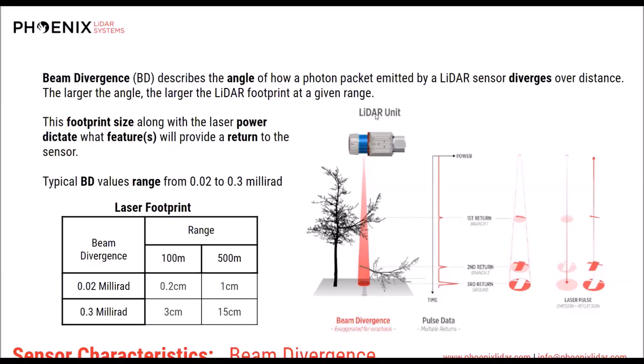But in terms of that absolute number, that's a pretty tough one, especially given the specific project areas, because you want to target clear, hard surface areas in your project to place ground control points on. But from my post-processing point of view, putting my idealistic hat on, I'd love to see at least 20 ground control points in a given scan. Obviously, much more if you're looking at thousands of acres.